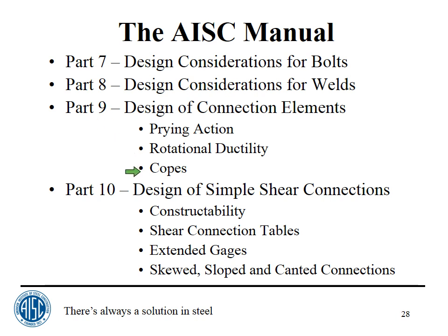And it's got a whole set of tables that allow you to come up with the properties of the sections of, say, coped beams where the top flange is coped, so you have a T-section. There are properties in there to make that design simple.